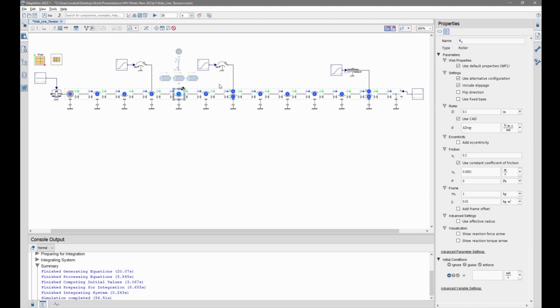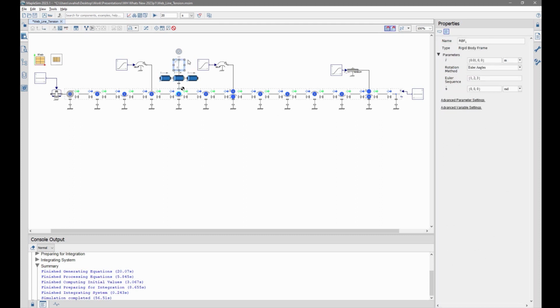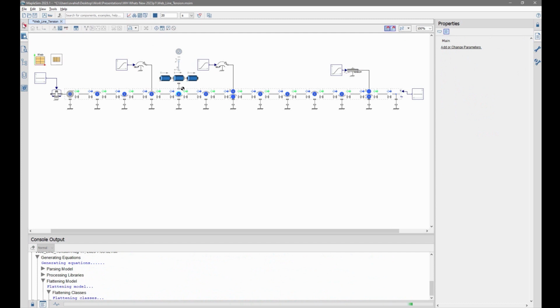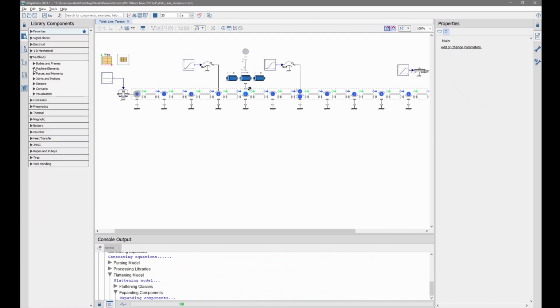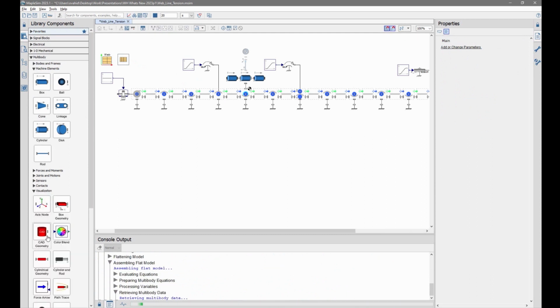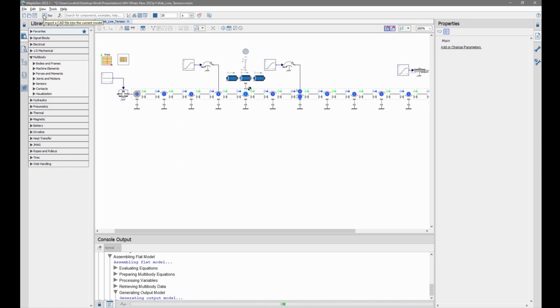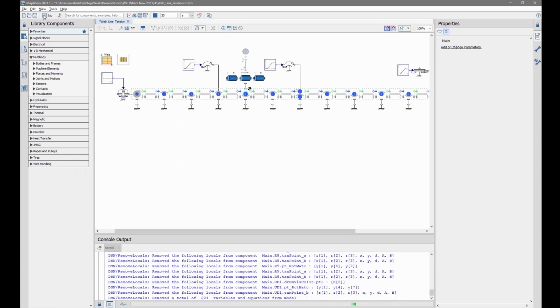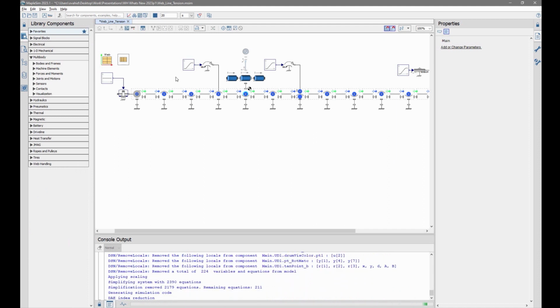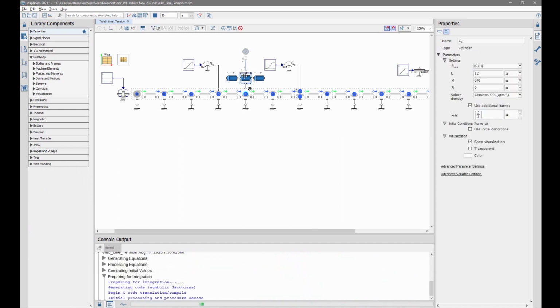I'm going to turn on the use CAD option, which removes the internal parameters, and now we activate these 3 cylindrical objects that would create a non-standard shape for our roller. Just a demonstration. I didn't use CAD here, but we are currently using the machine elements component from the multi-body library. Or we could have used the CAD geometry component, or we could just import an assembly using the import CAD add-on to MapleSim, and then hook one of those CAD geometries in the assembly to this component to complete the equations of motion for the system.